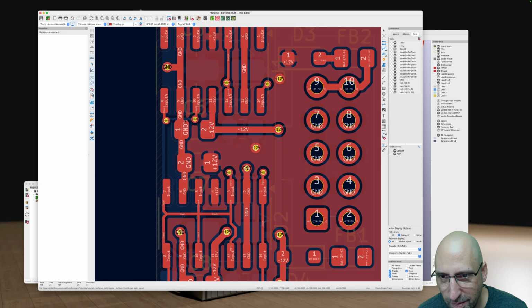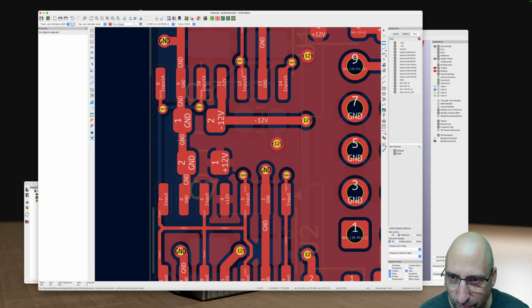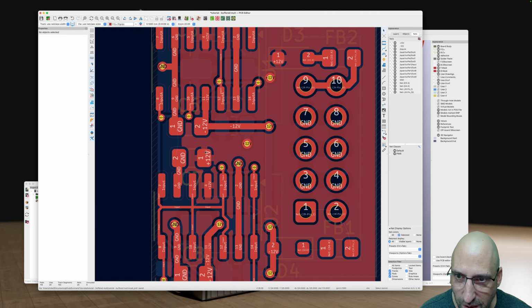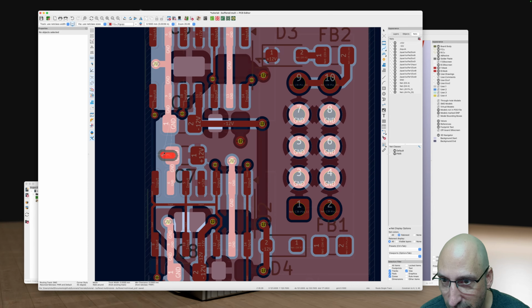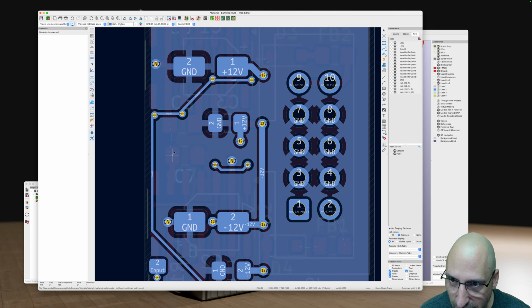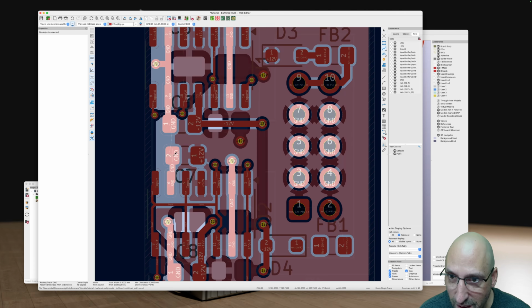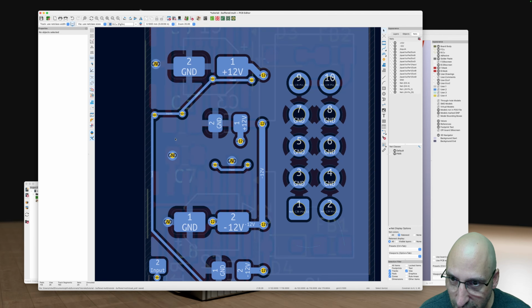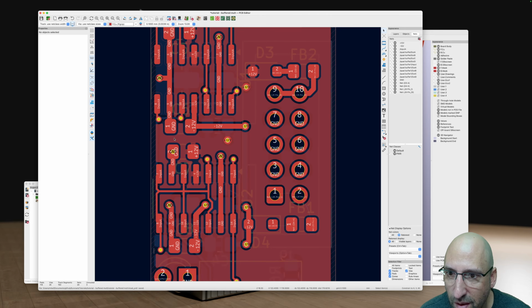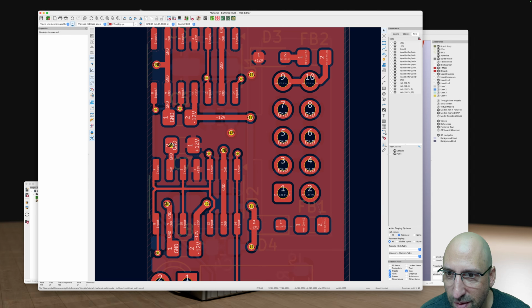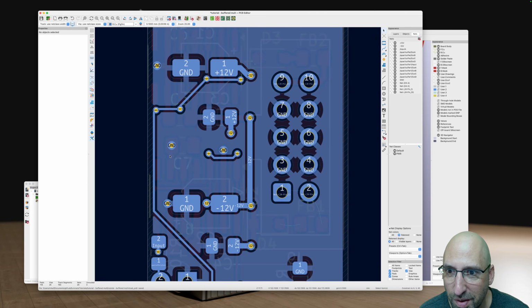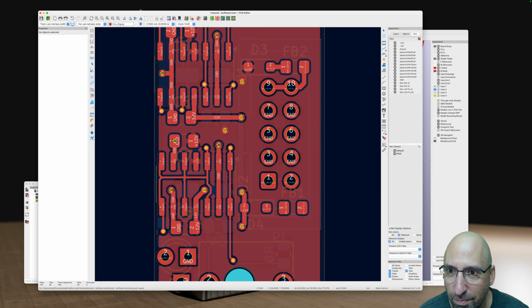So to get that filling, might be another way to connect. So I could potentially, on these big pads, I actually don't mind that much, just slapping a via in the middle of it. Great. And now they're all connected via the backplane again.